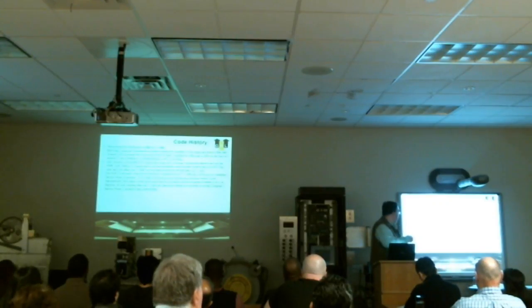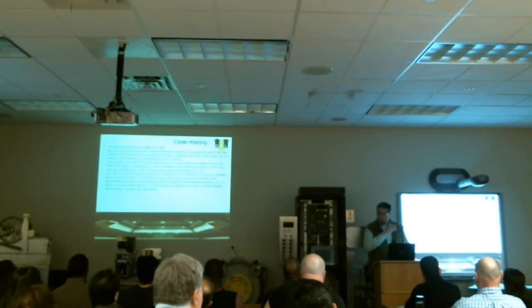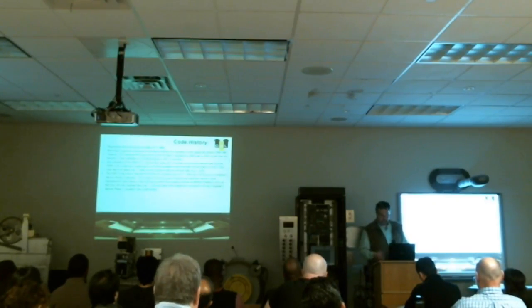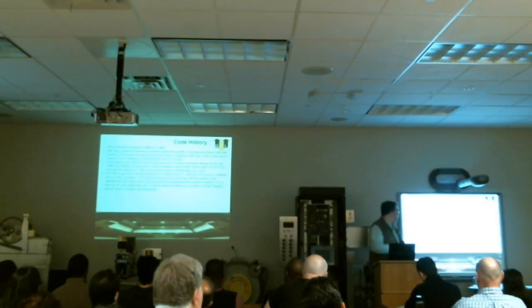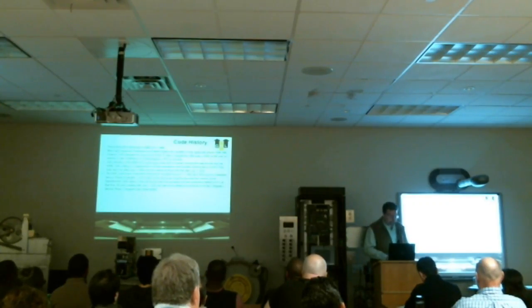So New York City says, give me door lock monitoring, but have it not work on phase 2, fire service phase 2. Now that was kind of an unwritten rule. They never made it official that they did not want it to work under phase 2. So some control manufacturers complied, others had not.